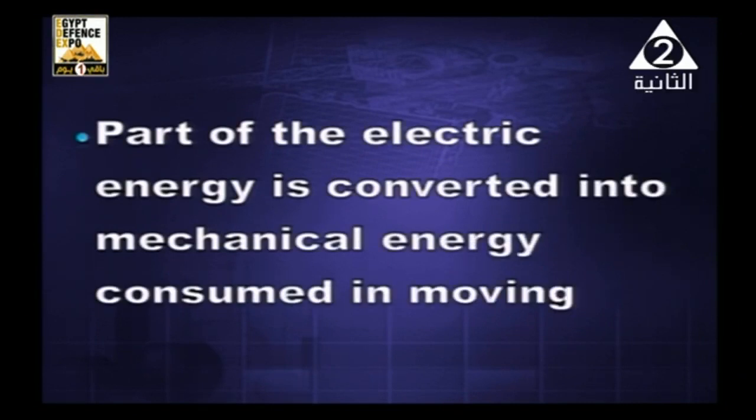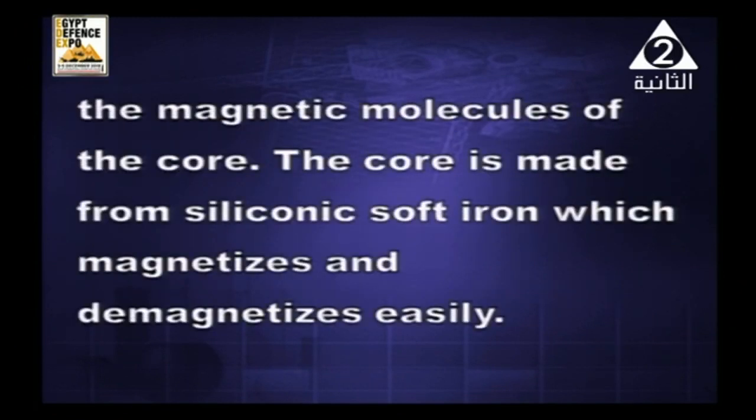Also, another conversion here: part of the electric energy is converted into mechanical energy consumed in moving the magnetic molecules of the core, in magnetizing the core. The core is made from silicon soft iron, which magnetizes and demagnetizes easily, to reduce this loss of power.